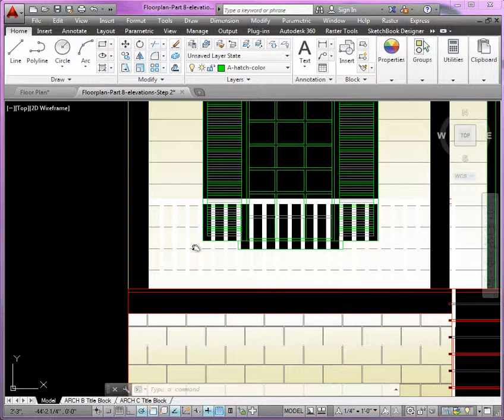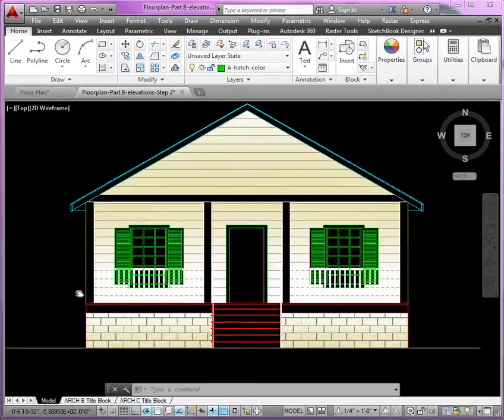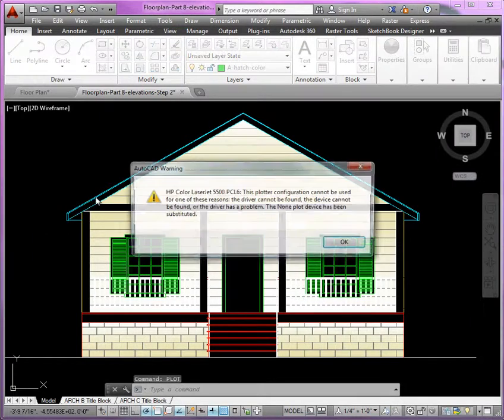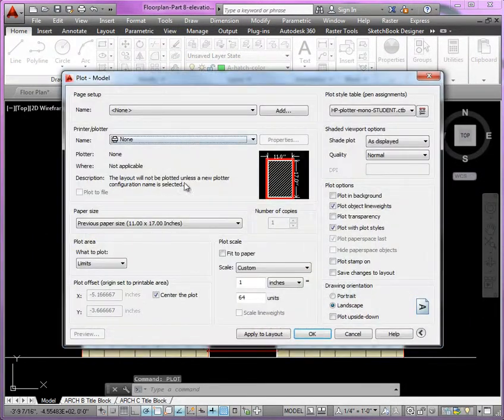So you can see how important it is to use layers, right? Because as you set the draw order, right now I have 4 or 5 things on top of each other. But I got to be able to pull the rail and the hatch towards the front, the window and the gradient hatching and the other pattern towards the back. But remember, with the color, it has to be in the back and the pattern in the front. Now, just to give you a sense of what's possible, take a look at this preview and then we'll be done. So if I go plot and just take a look at a quick preview here.